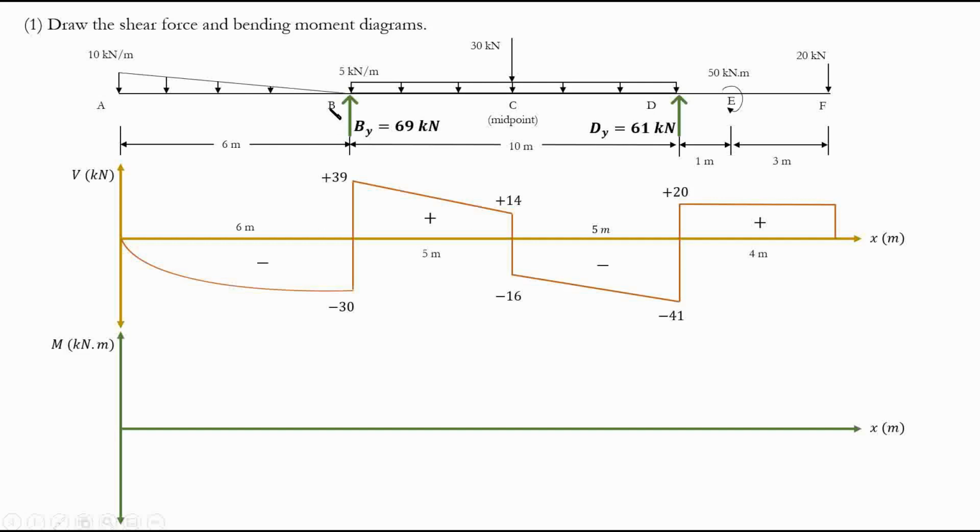Of course, we will have a shear going down. We have a moment in this direction, which is counterclockwise, basically in the direction of compression at the top. What is that moment? Of course, that is a conventional moment. In that case, the moment will be negative, which is exactly the case here. We're going to deal with a negative moment. We're going to talk about it, so I don't want to confuse you with all those conventions. But we have a moment here. That's the final idea. What is that moment?